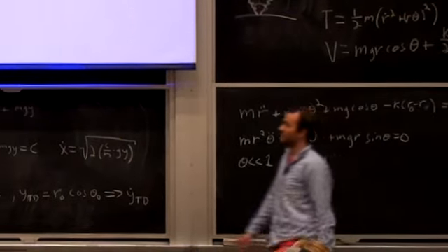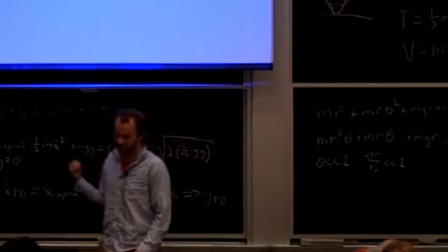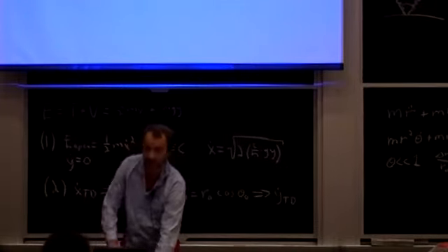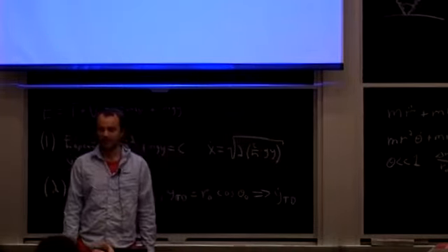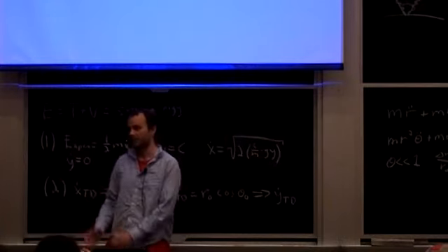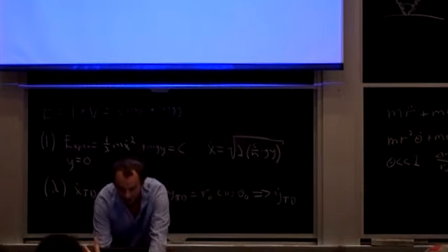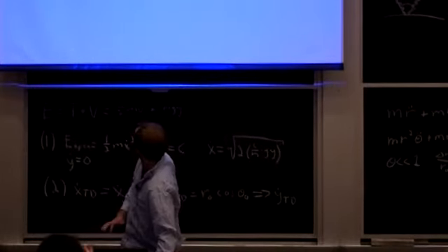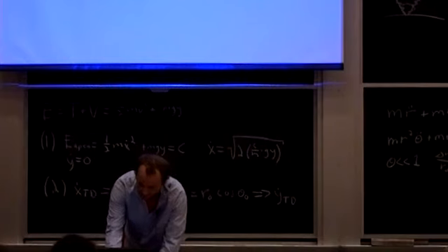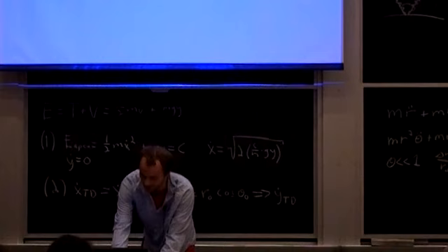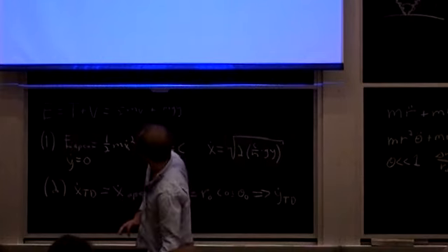And actually a number of people thought that a conservative system like this shouldn't be able to get that sort of stability. Because if you remember in the rimless wheel, the energy loss was critical towards achieving the stability. When you went faster, you hit harder, you lost more energy. And when you went slower, you didn't lose as much energy, so you were able to speed up as you went down this ramp. So the fact that you can achieve stability in this system is kind of cool too, because it's completely conservative, yet somehow the dynamics are able to push it towards a repeatable state.